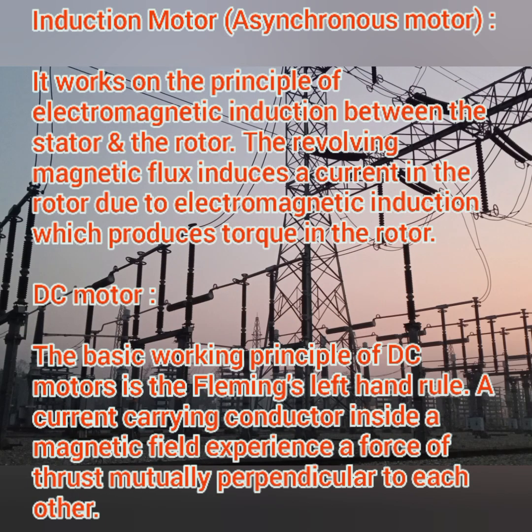Next is your induction motor, which means your asynchronous motor. It works on the principle of electromagnetic induction between the stator and the rotor. So the revolving magnetic flux induces a current in the rotor due to electromagnetic induction, which produces a torque in the rotor. This is the working of your induction motor.